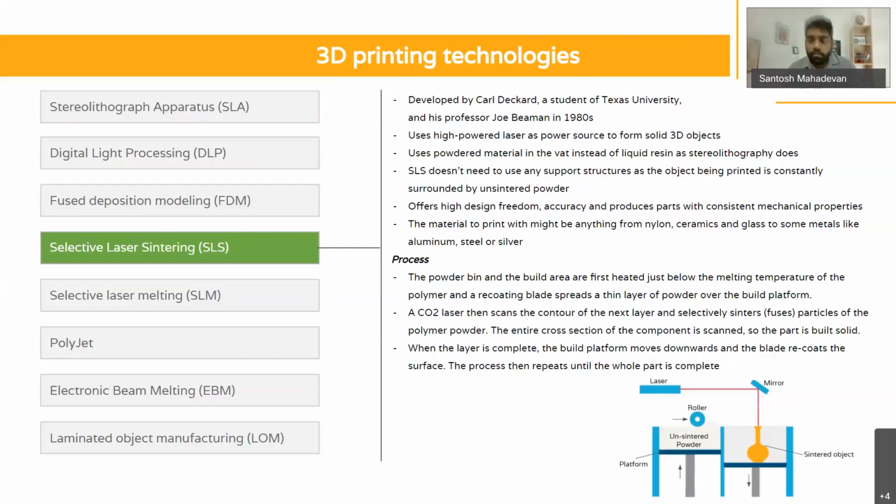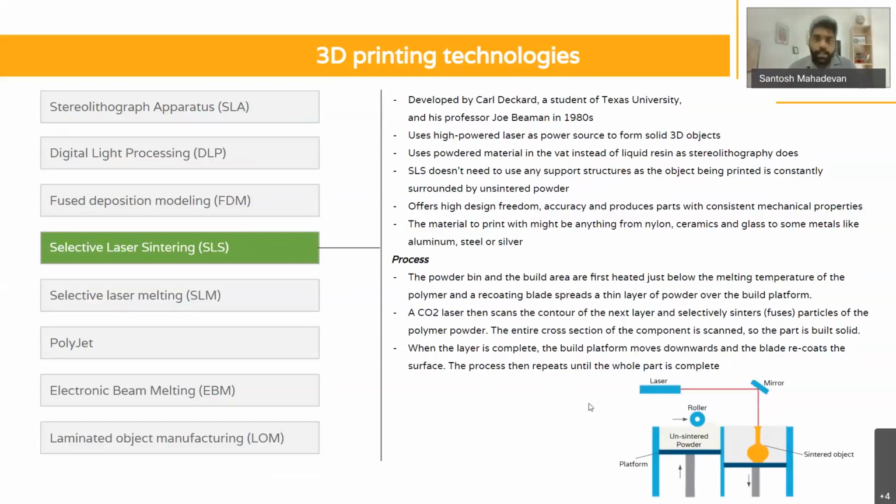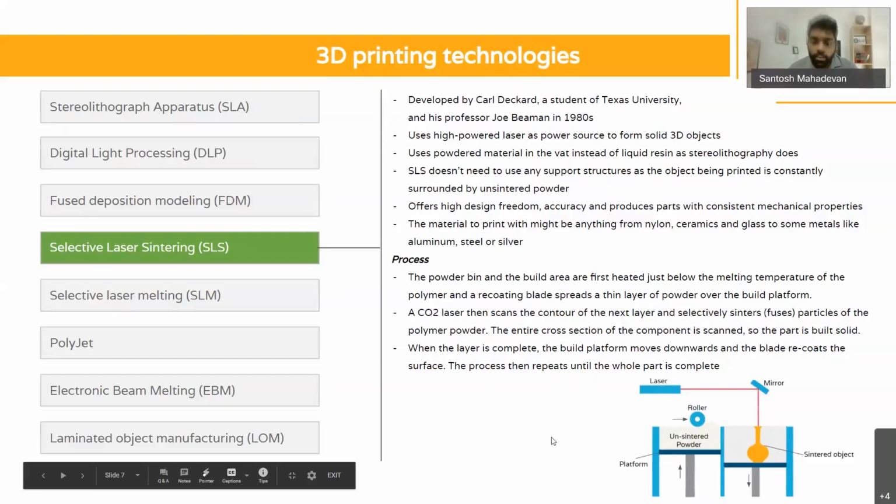To give you clarity on what I'm trying to explain, imagine you have a part in the shape of a reversed L. You're first going to create the vertical column and then the horizontal column. As 3D printing always involves putting one layer on top of another, you can guess that each layer supports the subsequent layer.